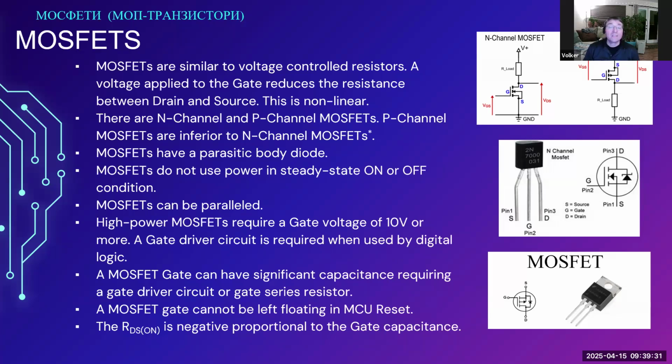The problem is the gate capacitance. We're trying to use the MOSFET as a switch at high frequencies, because we need a high frequency to power the motor without the motor vibrating. We need high frequencies for lighting, so hundreds of hertz in this case, that is not that high of a frequency.